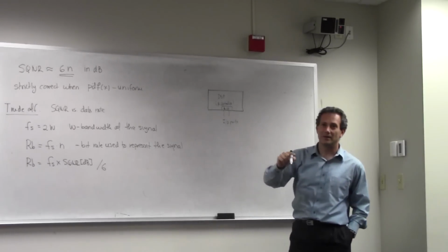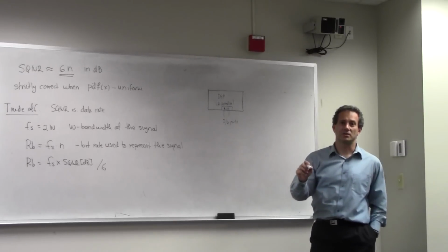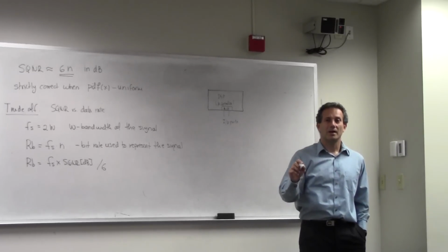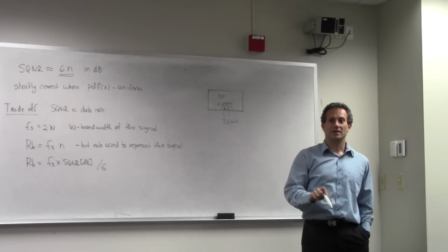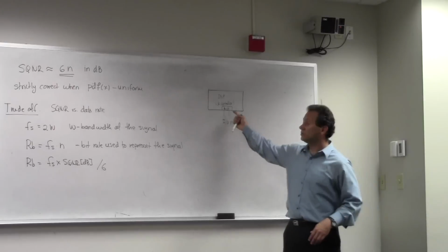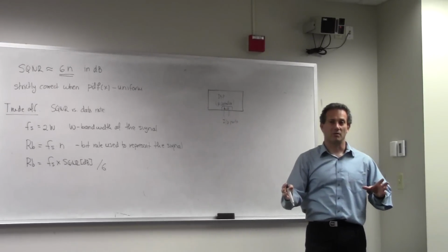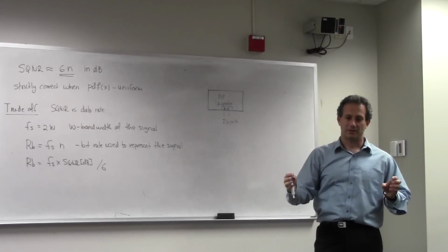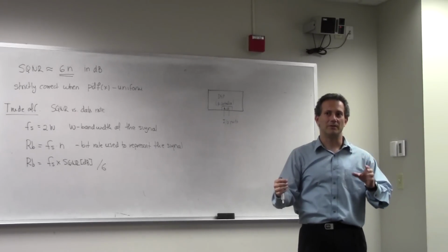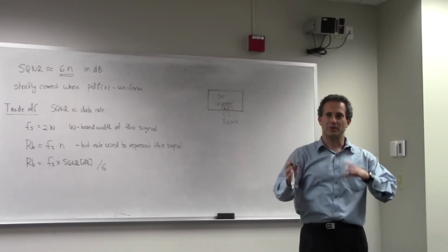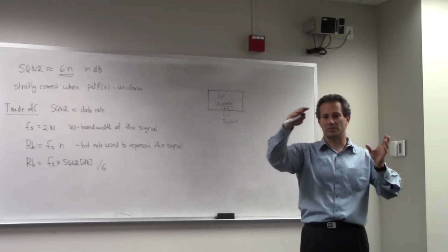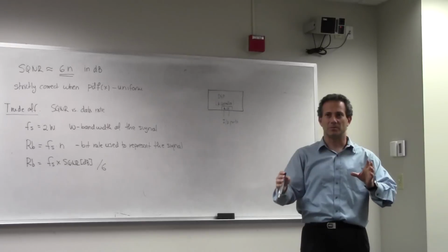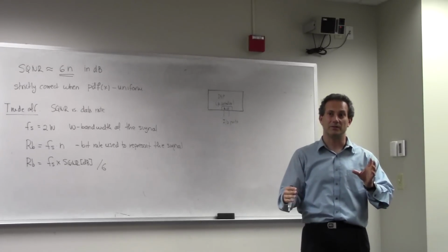It's okay, we haven't got to this point. When we design quantizers, we always design them as uniform. And the way we deal with the fact that the signal has a non-uniform PDF is we pre-process the signal itself. Remember, A to D converter is the process as a whole. And one of the things that you want in A to D conversion is for it to be really fast. So you cannot be messing with signals. It can be, for example, a resistor ladder or something really simple so that it can spit out these levels relatively fast.